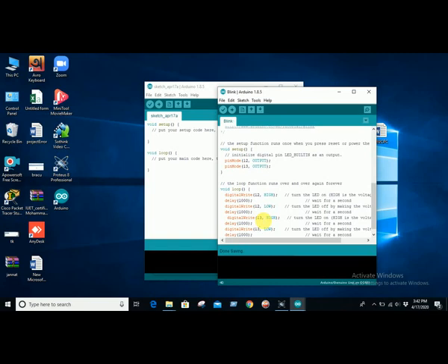So in this work we actually do blinking. For doing blinking, we use just two lights, on two pins. The first pin is 12 and the second pin is 13. In this section we say the first pin will be on for 100 milliseconds, and then off for 100 milliseconds. Then 13 number pin will be on for 100 milliseconds, and 13 number pin will be off for 100 milliseconds. Done. So this is our actual code.